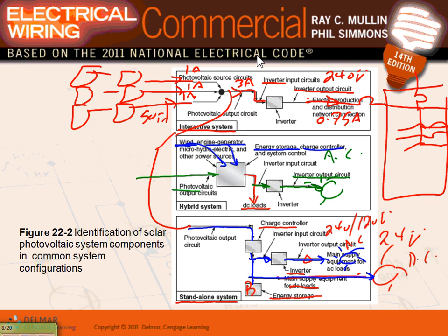No, what I'm saying is the portable inverter, the 3,000 watt inverter. Which 3,000 watt inverter? They sell some inverters in town. Understand? As long as, guys, these are specialized. This one is interactive. The inverter has 2 things. You have to capture the DC voltage and current, it has to be rated for the DC voltage and current on this side, and the AC voltage and current on the other side. If you can match the AC voltage and current here and here, match it to your power system here and your generation system here, you can use any inverter.